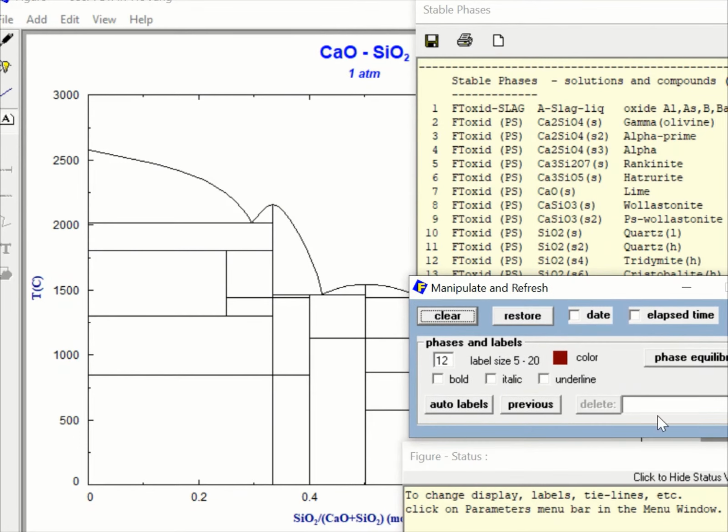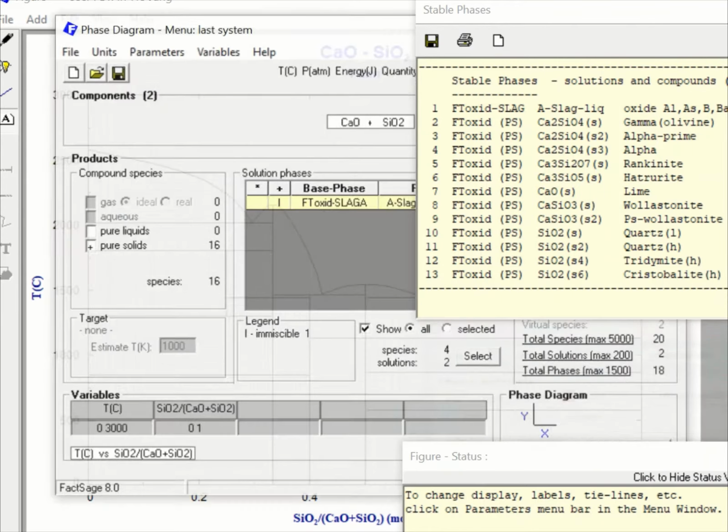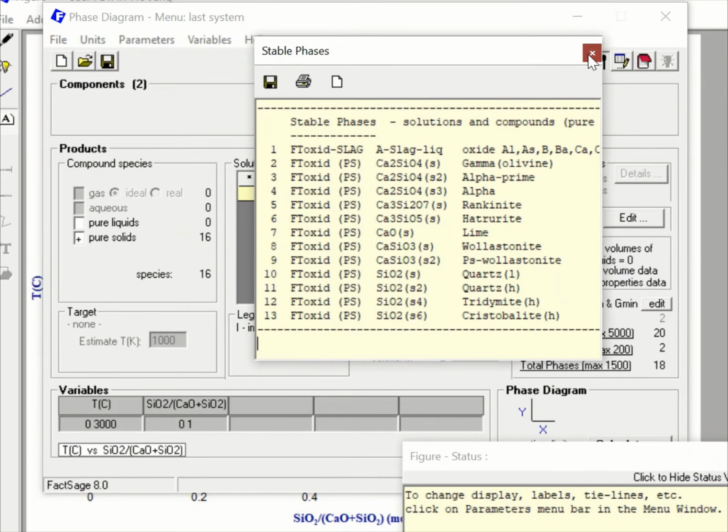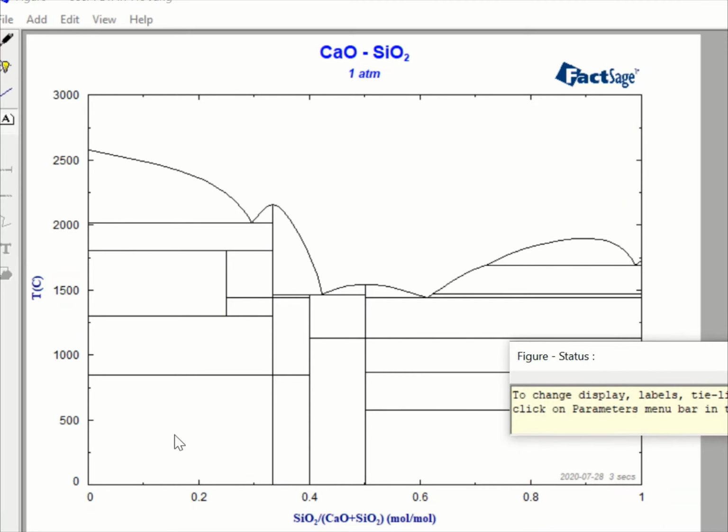And this is also an option you can select to get this one. This shows some cosmetic functions in the phase diagram. If you don't like it, you can just unclick it and remove it. I don't need this one. And here, as soon as you do the thermodynamic calculation, if you move the mouse, sometimes you can see this kind of dotted line. All these dotted lines are the tie lines in the phase diagram.